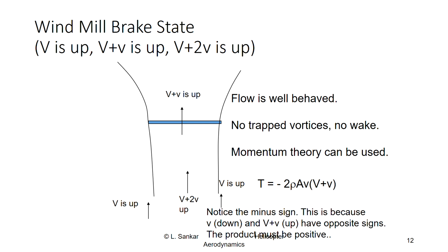So they don't bunch up either above the rotor disc, like the turbulent wake structure. They don't bunch up below the rotor disc, like the vortex ring state we saw before. You get a nice clean flow. No more forming and bursting of vortex rings. So now we get a steady state solution.